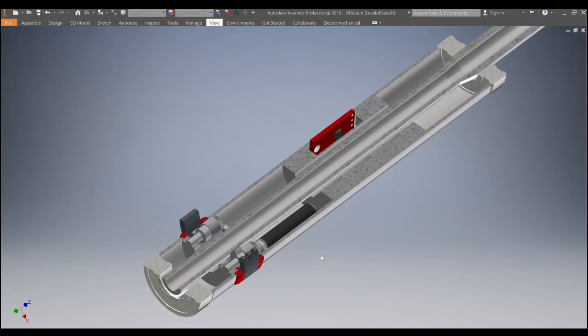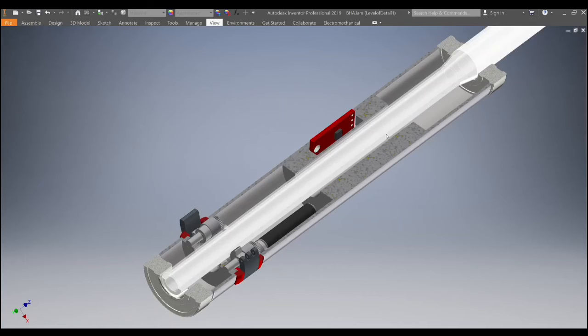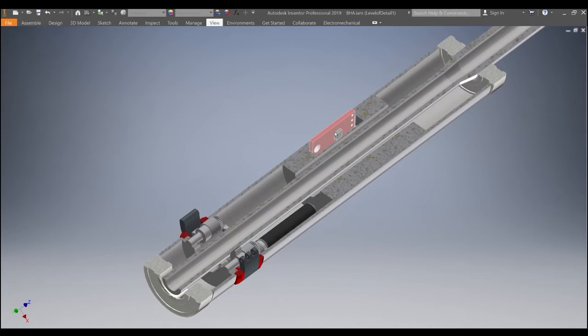We will be using a push-the-bit BHA to satisfy the directional drilling requirement, which is to trigger up to 30 degrees inclination, 15 degrees azimuth, and 10 inches horizontal lateral displacement. The push-the-bit configuration will include a 10-inch rotary steerable section in the BHA. There are sensors in the upper annular housing and 4 steerable pads in the lower annular housing. This section will be stationary, isolated from the rotary parts by radial bearings.